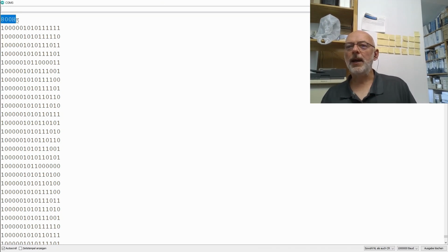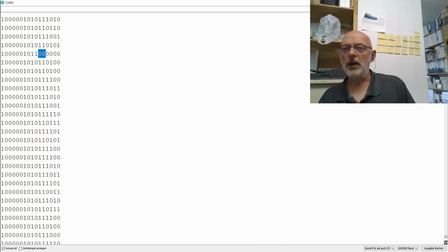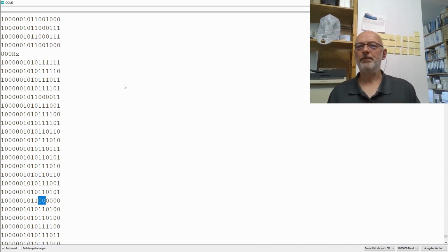And at 800 Hertz, the 5th and 6th bit are also flipping sometimes. But of course, that's a carryover from the 5th bit flipping now and then. Let's scroll down a little bit further. Yeah, there it's stable. Let's call that, happened 2 times, 4.5 bits of noise.